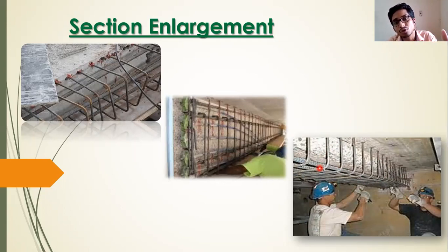Now how do we know how much of the concrete has deteriorated? For that, different types of tests are there. We should be very patient before adopting any method. We have to do all those tests. We have to take a lot of core samples from different areas. We have to see what the different deterioration mechanisms are that are happening inside the concrete system.